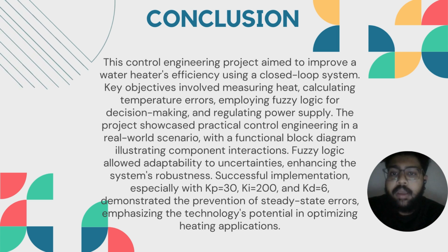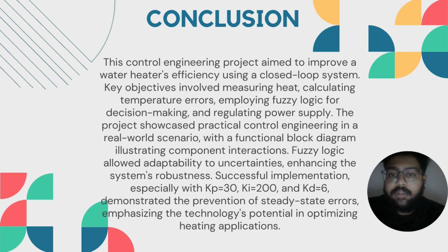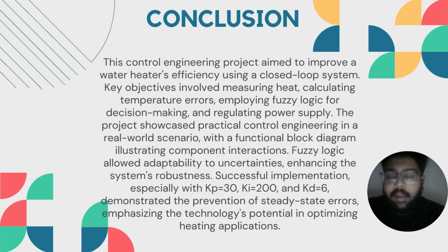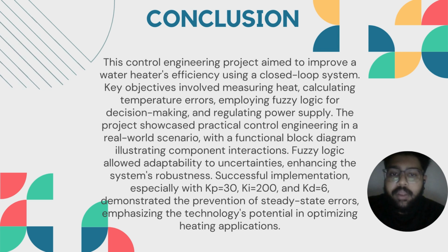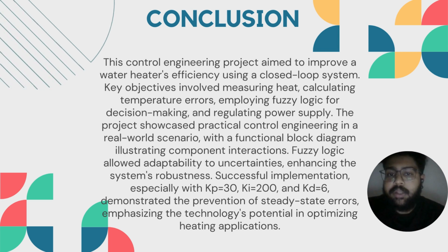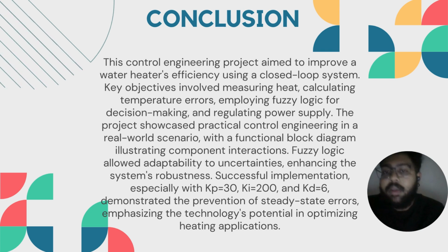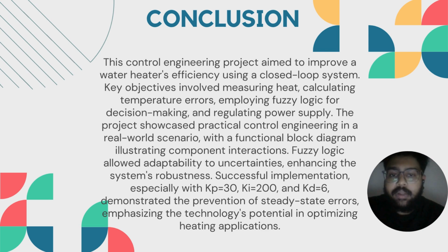The project showcased practical control engineering in a real-world scenario, with a functional block diagram illustrating component interactions. Fuzzy logic allowed adaptability to uncertainties, enhancing the system's robustness. Successful implementation, especially with KP 30, KI 200, and KD 6, which we found demonstrated the prevention of steady-state errors, emphasizes the technology's potential in optimizing heating efficiency.